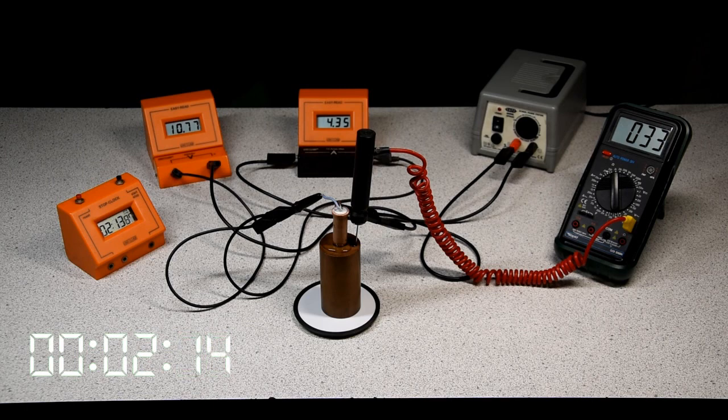The energy calculation will be simply the reading of the ammeter multiplied by the reading of the voltmeter multiplied by 5 minutes. But 5 minutes is equal to 300 seconds. The calculated units for the energy change, delta Q, will be in joules. After 5 minutes, the final temperature can be noted, and the temperature change, delta theta, can be calculated.